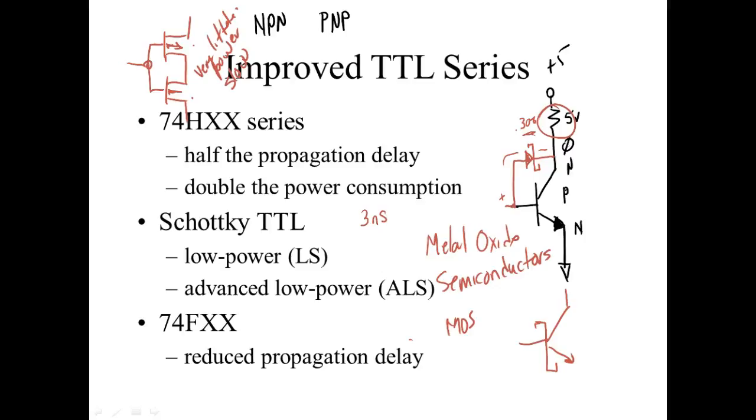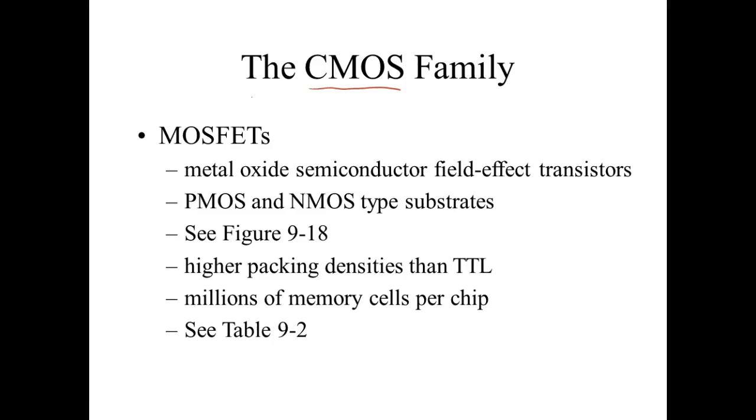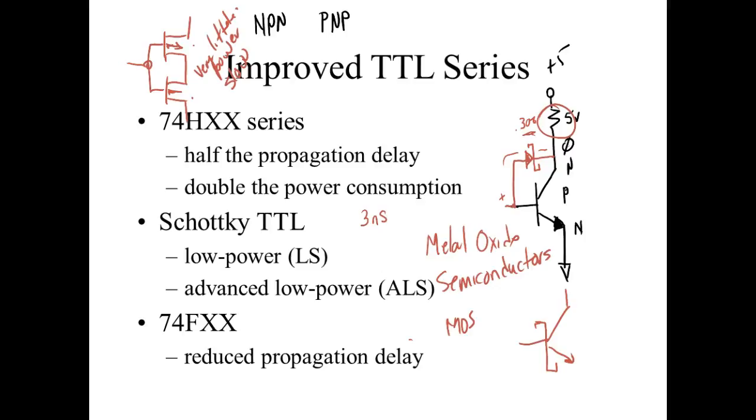Which they usually do. Another thing that was nice about CMOS is the range of voltages we could operate this thing on. These guys here could operate on like any voltage from around 3 volts up to 17 volts. TTL had to be 5 volts plus or minus 5%. CMOS, since these are voltage controlled devices, they're not current. So what a MOS does is, a bipolar transistor uses a current to control a current.